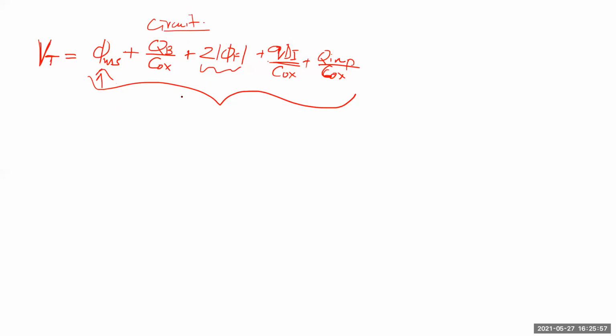Body effect, yeah. Only the length and the area we can control. Okay, so the length and the area of the MOS, right? That's the gate area you're talking about, I guess. Let's say this was your source and drain, L, and this is your gate. Where is W and L in this picture? So I should be precise. VT0 is for VSB equal to 0 volt.